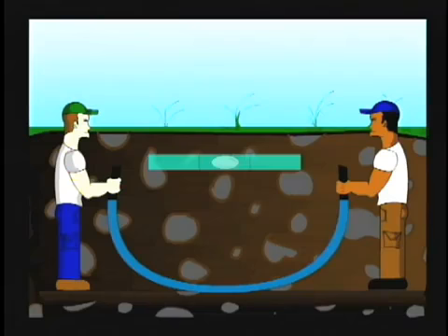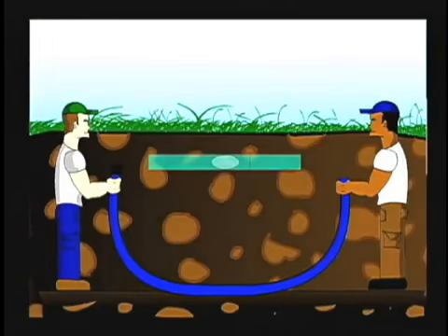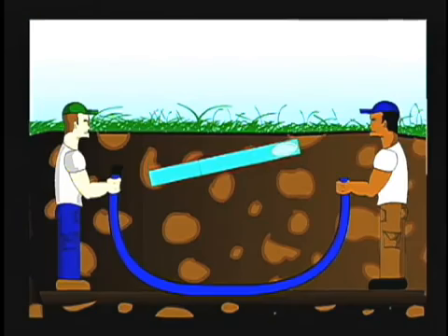The water hose technique is widely used. The hose forms a long U shape in the trench. When it is filled with water, the 2 water surfaces at either end of the hose will be at the same elevation. Measure down from this water surface elevation to get the proper trench depth. A manufacturer makes a kit of this type with screw-in ends, clear tubes, and marks on the tubes. This technique is easy, but it is a bit messy and time-consuming.